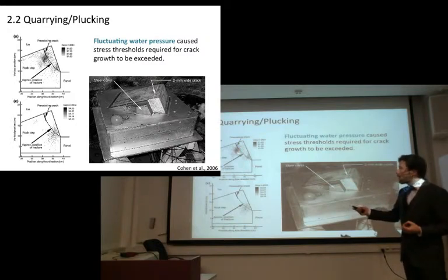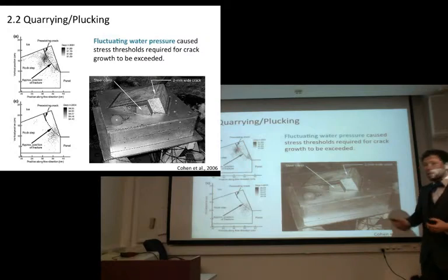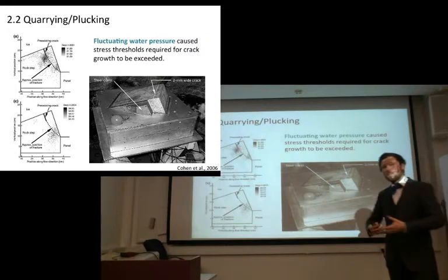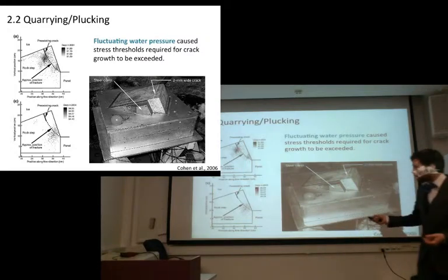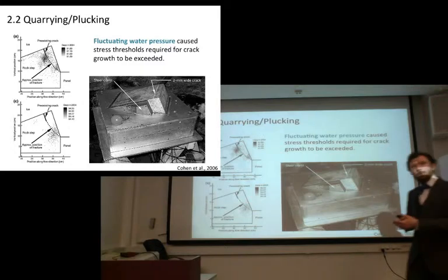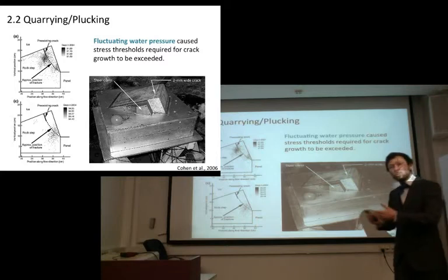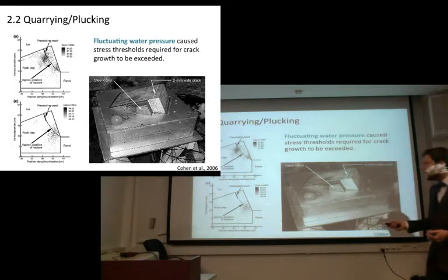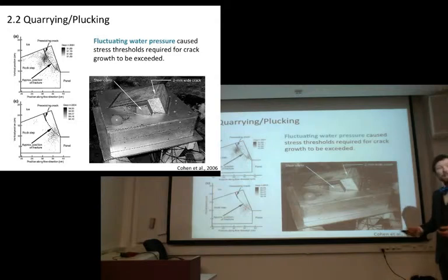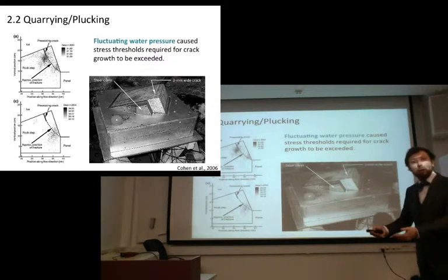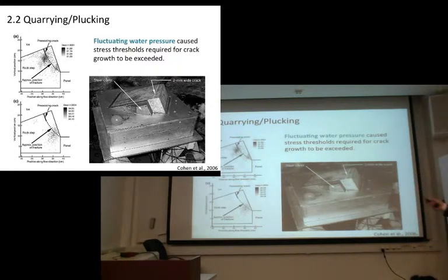At the beginning, just below the crack, it started to have a lot of activity and the crack was propagating. Then they could control how fast this crack was growing by fluctuating the water pressure. Eventually, these acoustic emissions were much further down. And when they recovered the block, this part here was eroded, plucked away. So it really confirms this relationship with water pressure.